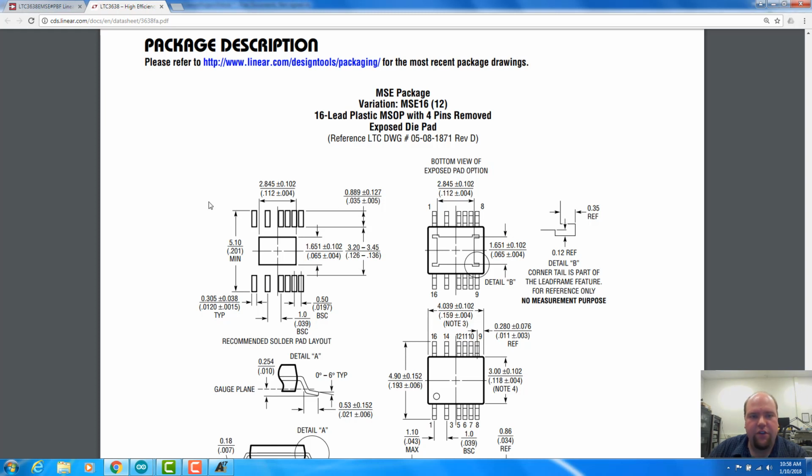So the first thing we're going to do is place all of these pads, knowing that our pitch here is 0.5 millimeters, and our center-to-center distance here is going to be 4.211 millimeters. That's going to make our lives a lot easier by adjusting the grid in Altium.